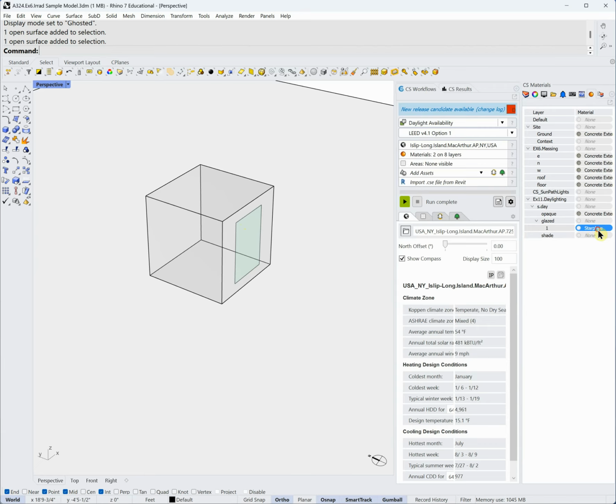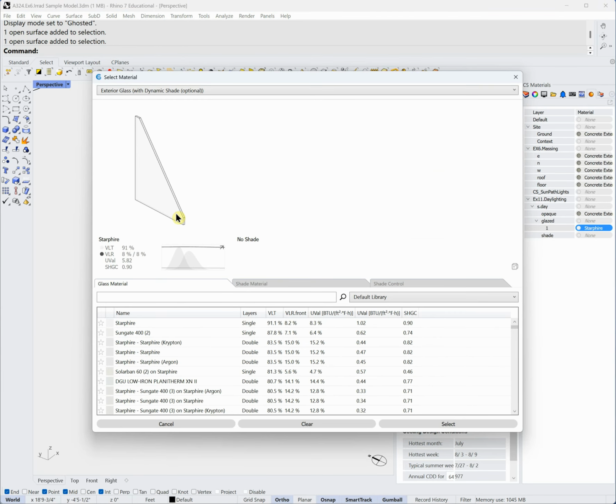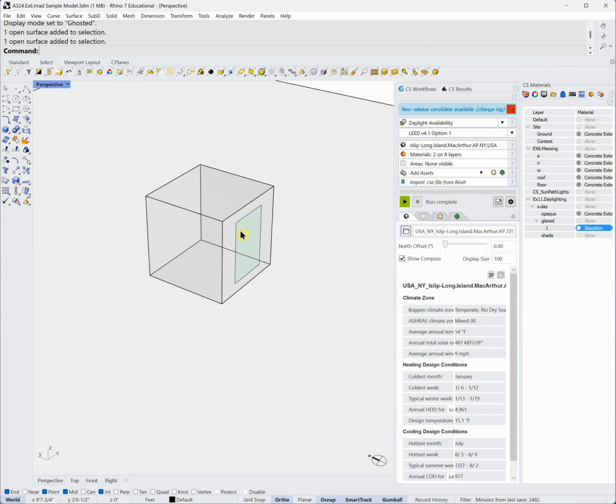If I were to want to have a triple pane piece of glass here, it's still going to be a single surface, because as we saw here, we are able to define the specifications of that surface by choosing these specs here. And if I were to add two more surfaces out here to emulate the thickness of that actual assembly, I would really be messing up my simulation, because I'd be actually having 9 panes of glass and they'd be separated. It wouldn't be a realistic estimate.